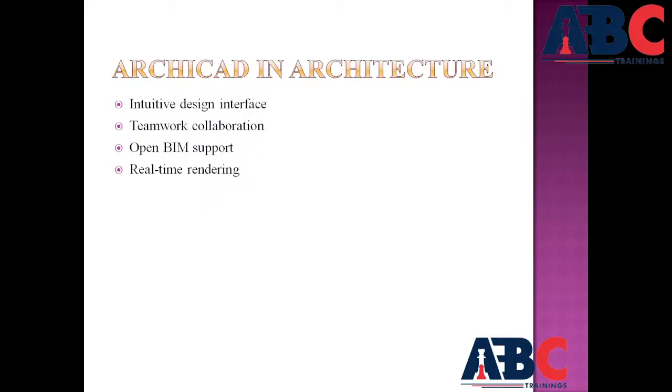OpenBIM and interoperability. ArchiCAD strongly supports OpenBIM standards using IFC, Industry Foundation Classes, and BCF, BIM Collaboration Format, for file exchange. This ensures smooth interoperability with BIM tools such as Revit, Tekla, and Navisworks, making ArchiCAD suitable for multidisciplinary projects. Next one is about visualization and real-time rendering.